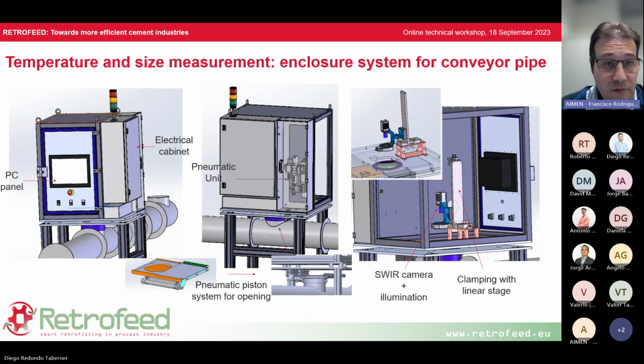yes, this is a system that will be integrated for measuring temperature and size in the conveyor pipe. It's quite different from the other one because it integrates a camera that is working in the short-wave infrared range. And this system is composed of a PC panel with an electrical cabinet in which there is a PLC system controlling the opening of a window, door, and air curtains in order to protect the enclosure from dust projection. This system could also be triggered automatically from the factory.